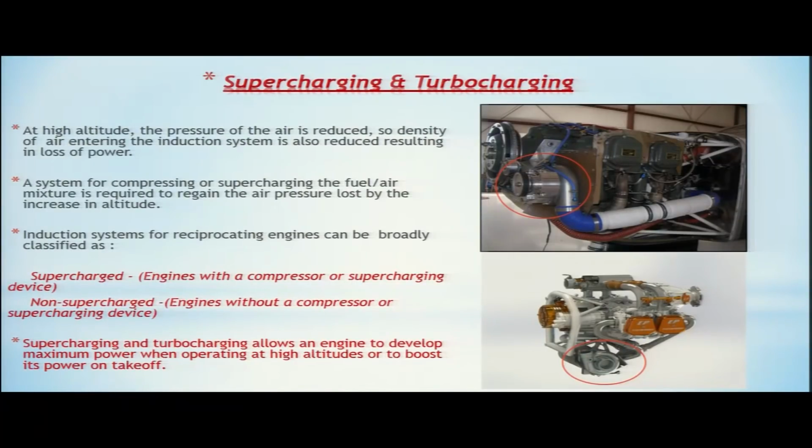Now, coming to supercharging and turbocharging. What is supercharging? What is turbocharging? Why is it required? Let us see. We all know that as we move to higher altitudes, the pressure of the air reduces. So, the density of air entering the induction system is also reduced, which results in loss of power.